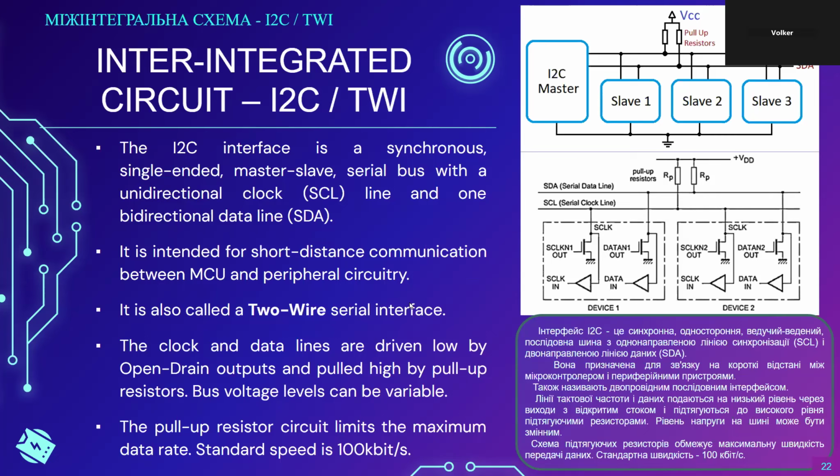So it is possible to use 5 volt I2C external devices with a 3.3 volt microcontroller. If you do that, of course, this would now be a 5 volt I2C bus. You cannot do combinations of using 3.3 volt external devices together with 5 volt external devices.